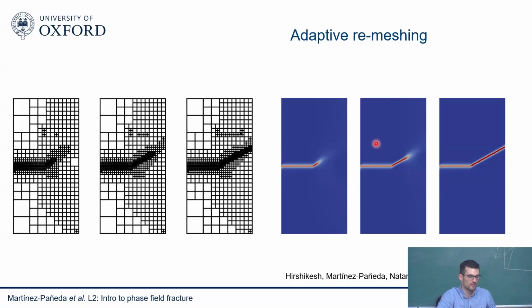That's what I'm saying. So normally, when I mesh, I just use a uniform mesh all over the place if I don't know where the crack is going to go. So what I would do, if I'm not using adaptive remeshing, is use maybe a mesh like this one, that I know is probably too coarse, but I'll put this mesh everywhere. Then I'll see that the crack is deflecting in that direction. So then I will use a mesh like this one over this square in the second calculation, and that will be the end of it. But you can also use these kinds of techniques where you start with a mesh like this, and then depending on the phase field, you start making your elements smaller, smaller, smaller, and then eventually you get the right result.